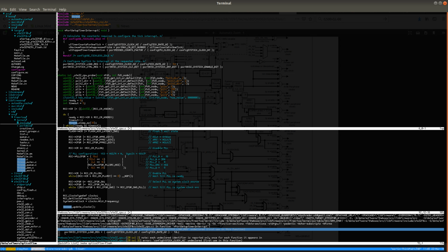and that would be in, or maybe can I include directly just the, if I have the include path specified on my compile command line, then I should be able to include FreeRTOS config.